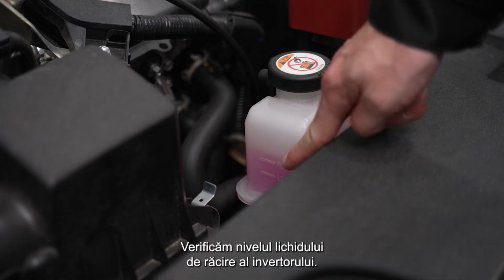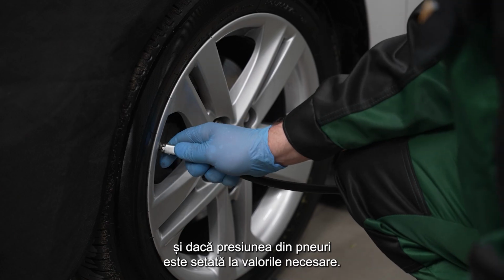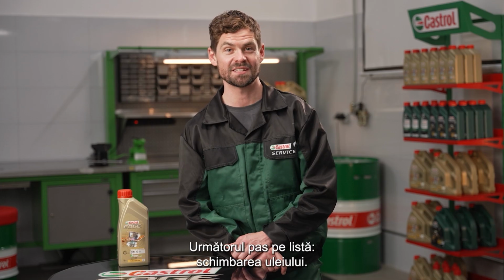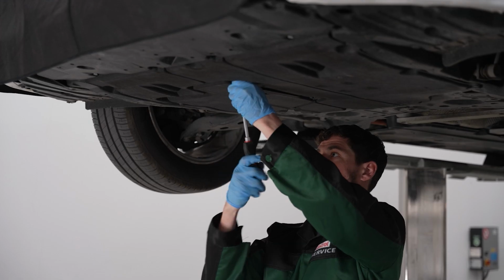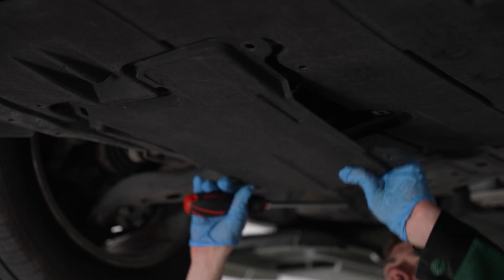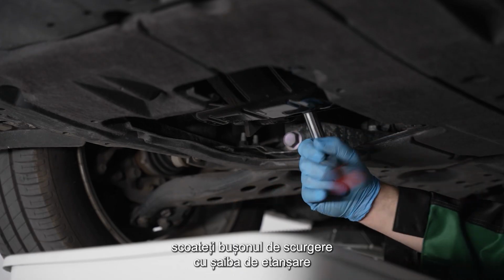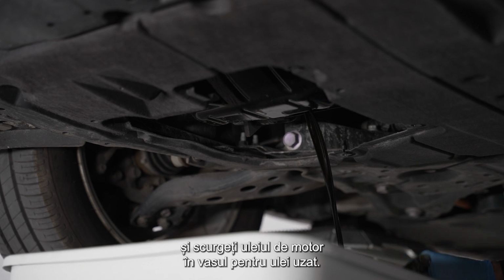First, we check the inverter coolant level. Then we check the thickness of the brake pads and whether the tire pressure is set to the required values. Next on our list, the oil change. After raising the vehicle using a lift, remove the drain plug with the sealing washer and drain the engine oil into the used oil drain.